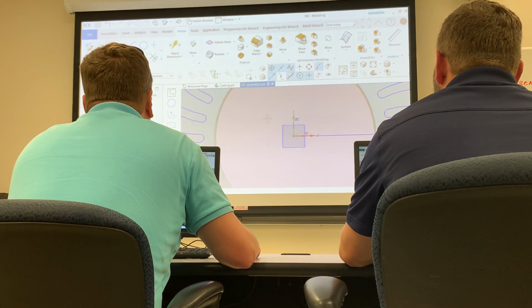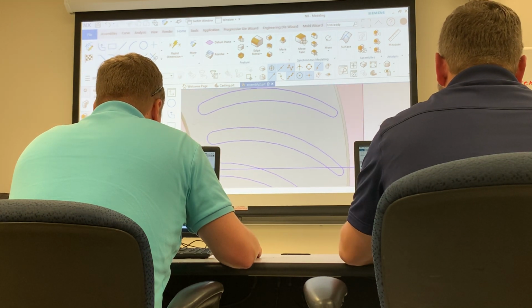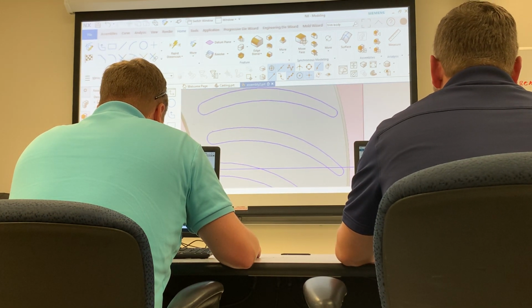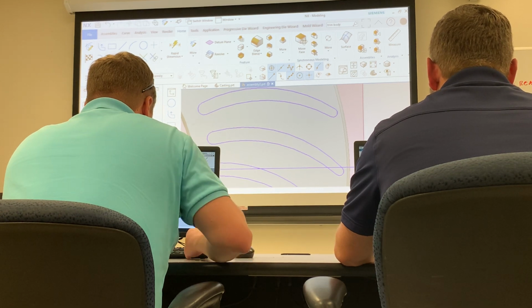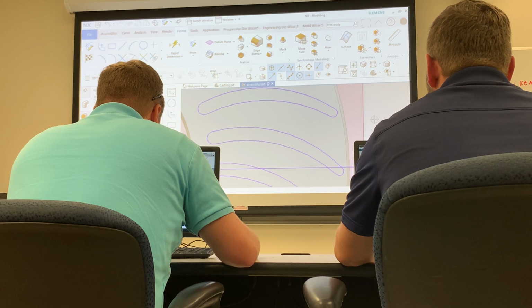Now I know you could go into the hole command and do a sketch there, but I'm going to do this a little differently. I want to do my sketch first, position my points first of all, and then later add my hole to pre-existing points.